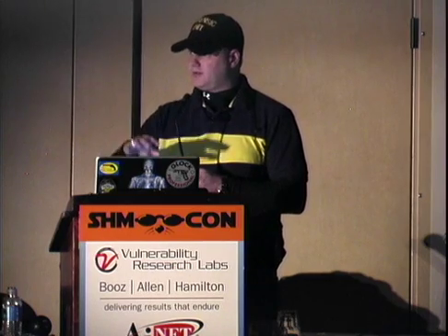If the drive fails, then we actually have some tables and a short that has to happen on the board in order to repair that. It doesn't quite do exactly what you would expect. It's not a perfect fix or repair. And then there is a third firmware problem. We can read the data in those other two instances, but there's this new third firmware problem that nobody has completely reverse engineered, or we don't have a large enough subset of the drives, but they do still fail, and we can't recover from them.